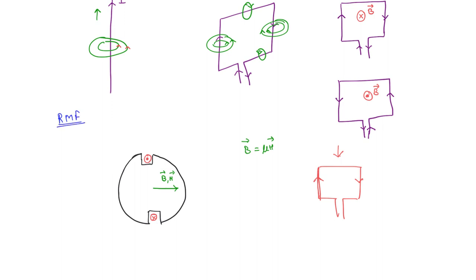We will make use of 3 coils. One of the coils is placed here. The other 2 coils we have to place in such a way that all the 3 are spaced at 120 degrees from each other. So that means this is the top end of the coil, right? We can see this line. Now the other coil will be 120 degrees. This angle here is 120 degrees. And similarly, you can get another coil at 120 degrees like this. So you can make rotor slots here.